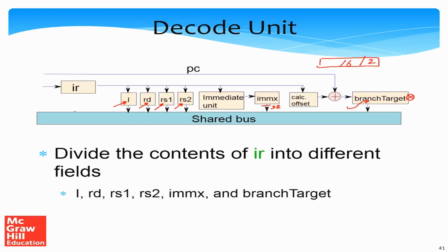All of these registers are connected on a shared bus. What is a shared bus? So a shared bus is basically a set of copper wires to which all of these registers are connected. But it is not the case that all of them are feeding their data to these copper wires, right? So then it will not work. So by default, these links between the register and the bus are actually turned off, or they are open circuits. But it is possible for us, as we shall see in the next few slides, to occasionally read these registers.